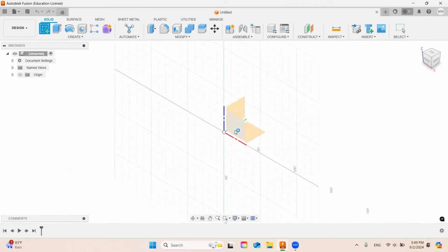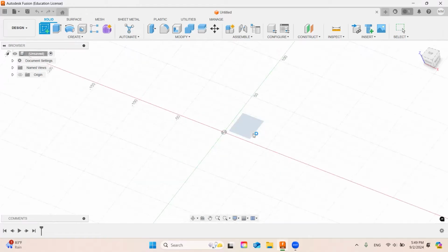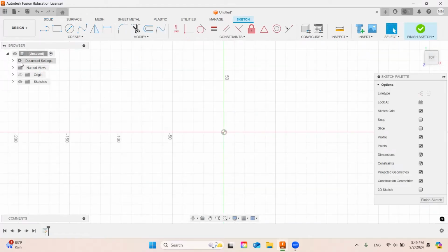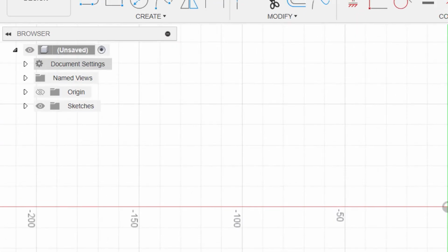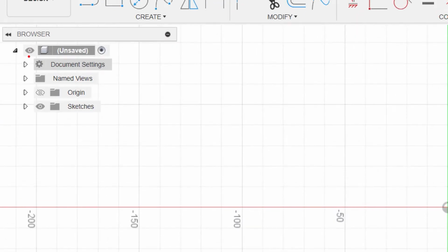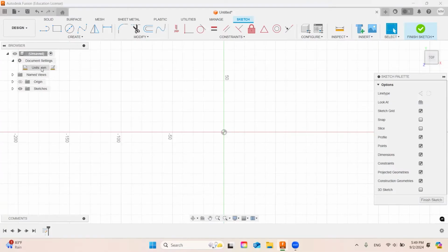You can see I have three different planes that I can use: that one, the right, the front. I'm gonna use this one, which is the bottom or the top face. Click that one. You also want to check your document settings, for those of you that haven't started. So make sure that you do check your document settings. If you click here, document settings, you open that little arrow, you should be able to find and change yours to whatever. In this case, I am working with millimeters. If you are in inches, just click millimeters, click as default, and that should be changed there.